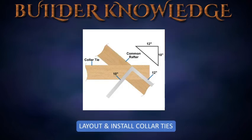Double the result to get the collar tie length in feet. Your math is this: drop in inches times 2, divided by unit of rise, equals length of collar tie in feet. Use a framing square with the unit of run and unit of rise of the common rafter to mark the collar tie to fit the slope of the roof.